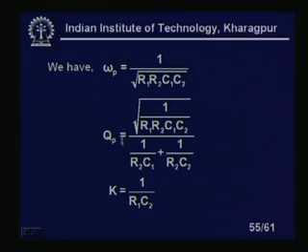These are called the filter parameters. Like at the beginning, as I said, if I buy a resistance, you have to tell its value. If I just say value, that does not make any sense. You have to tell the tolerances, you have to tell the wattage. Once you define all these things, more or less a resistance is defined. More precisely, you have to tell what type of resistors these are, whether these are wire wound resistors, or carbon film resistors, or any other type of resistors.